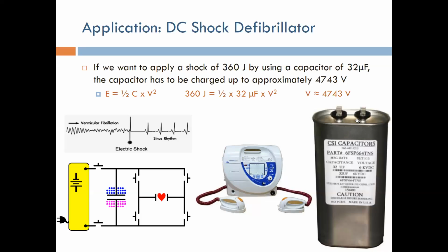Because if you touch it, it can electrocute you. Even if it's a DC voltage, if you make a complete circuit with this capacitor charged to 5,000 volts, you can have a big problem, okay?